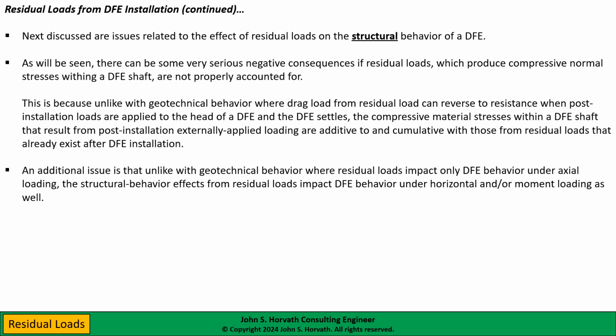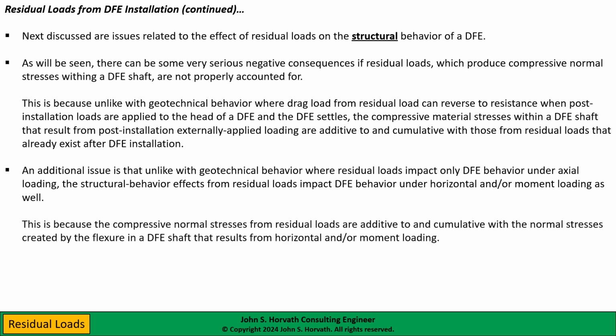Another thing is that, unlike with geotechnical behavior, where residual loads tend to impact only the DFE behavior under axial loading, with the structural behavior, effects from residual loads can affect the behavior of the DFE under horizontal and/or moment loading as well. And this is something I don't see talked about.